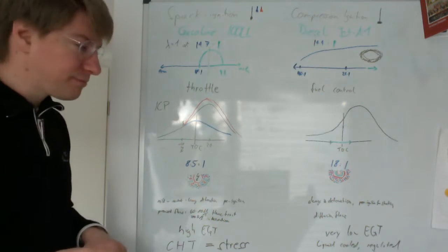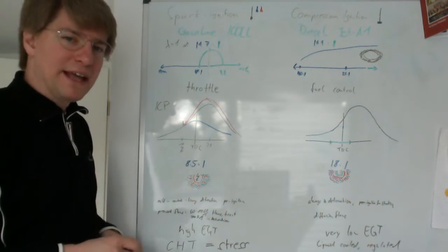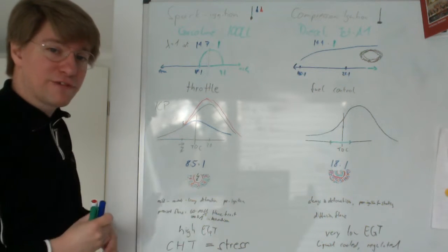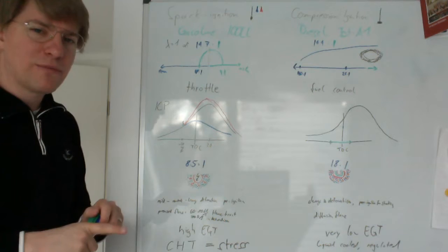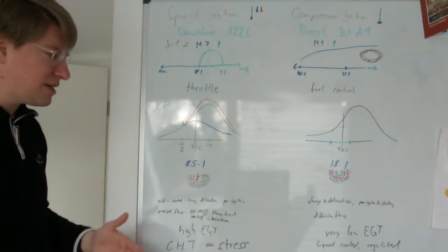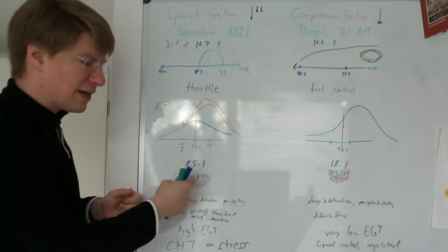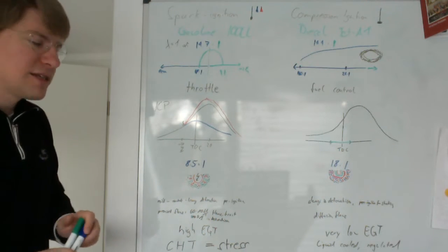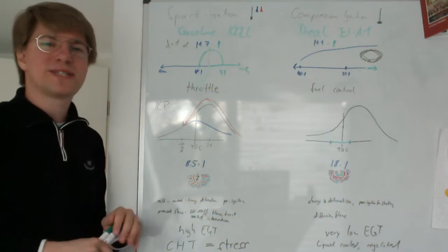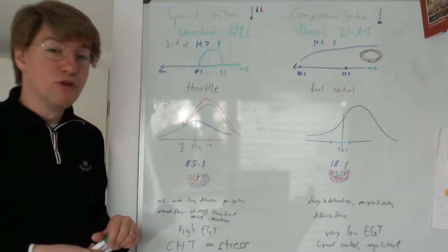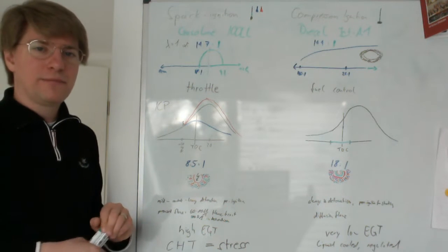What happens, excuse me, if we do this at takeoff power? So you have the flame front expanding away from the spark plug. That raises the pressure in the combustion chamber, of course, because this flame front is very hot and expanding fast, about 60 to 80 feet per second when the combustion process moves normally.